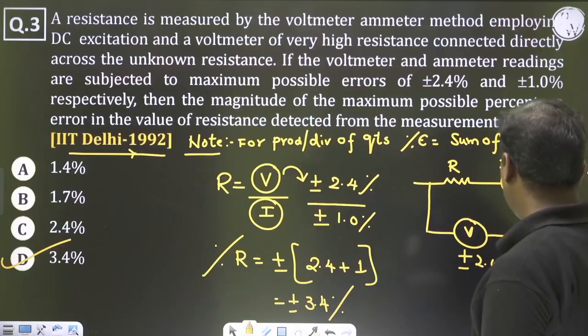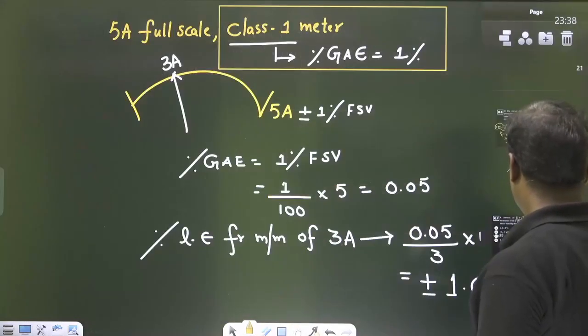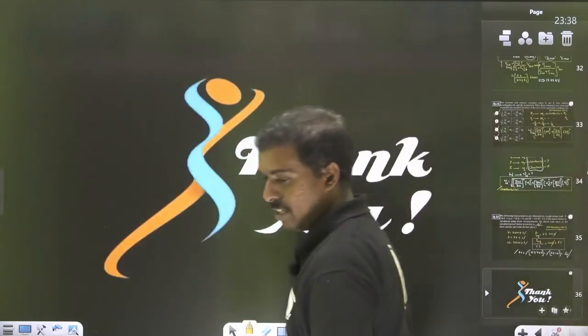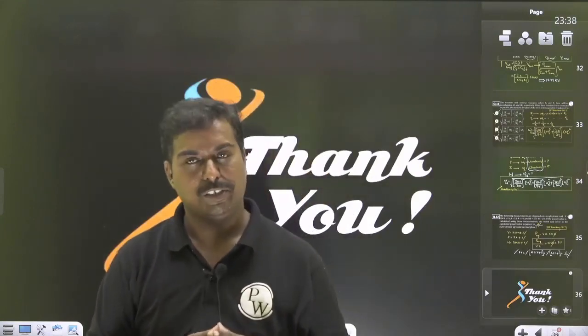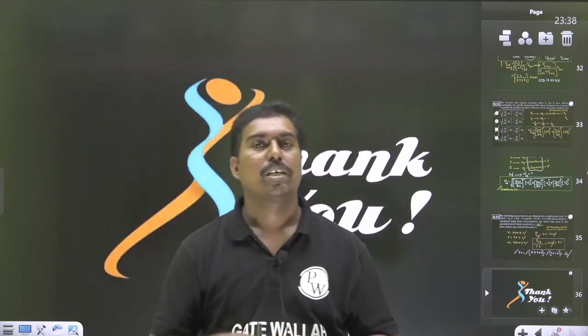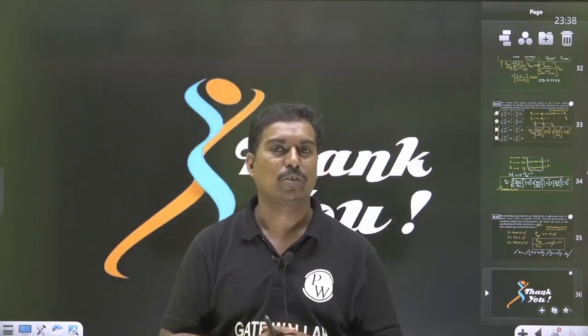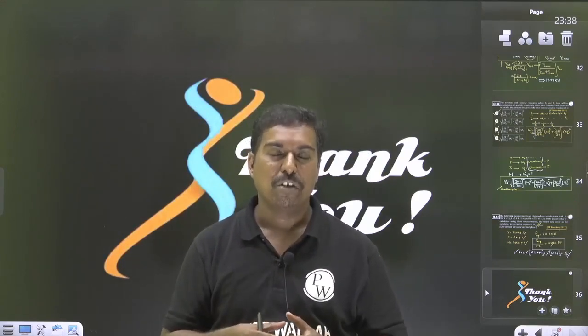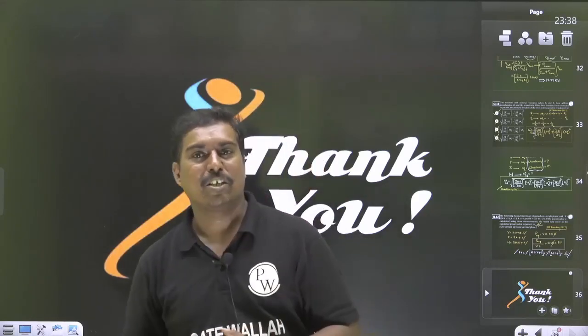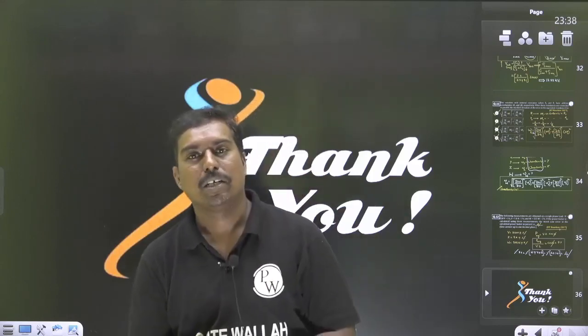So we have taken a list of questions on error analysis. I am suggesting, especially for instrumentation students, you are going to get some questions on error analysis with respect to non-electrical measurement. Sometimes they may give you flow rate measurement. Flow rate formula, Q is equal to area into velocity in a pipe. So there is an error in area measurement, there is an error in velocity measurement. Based on that, they may ask you to find out the error.